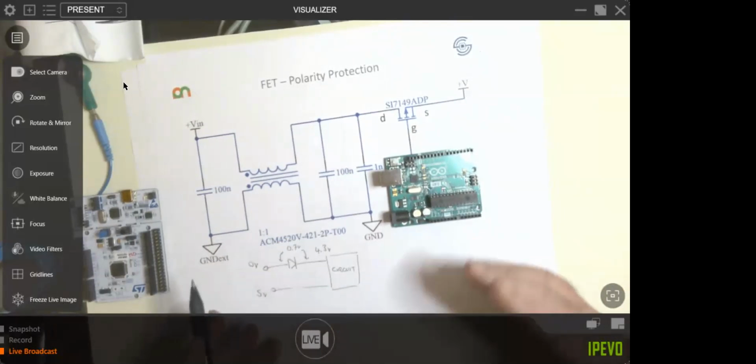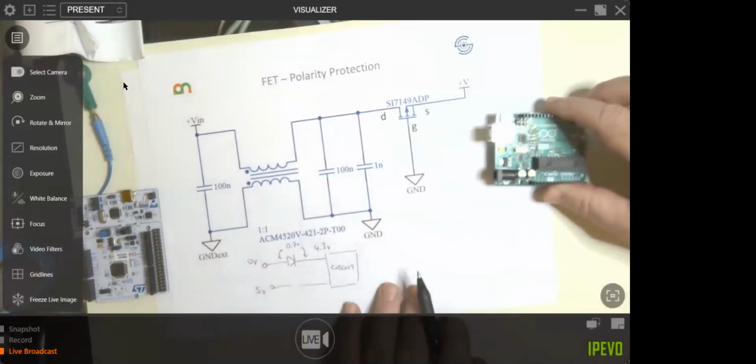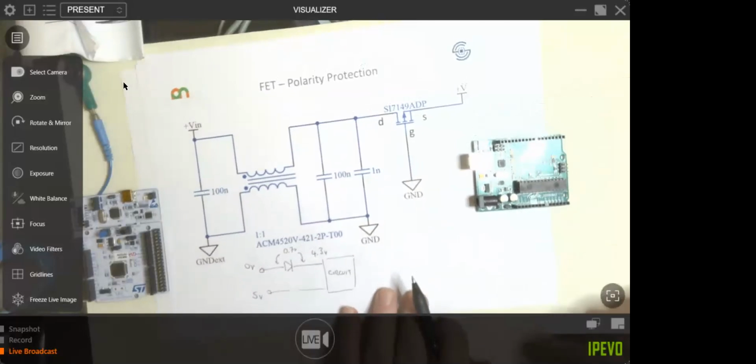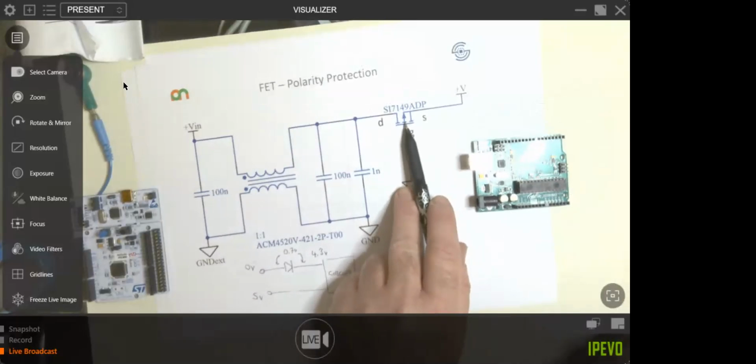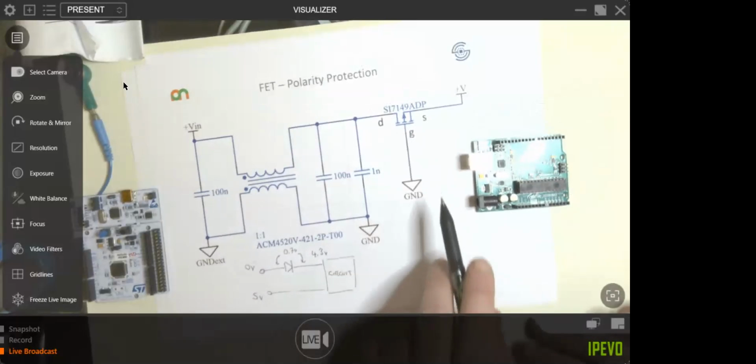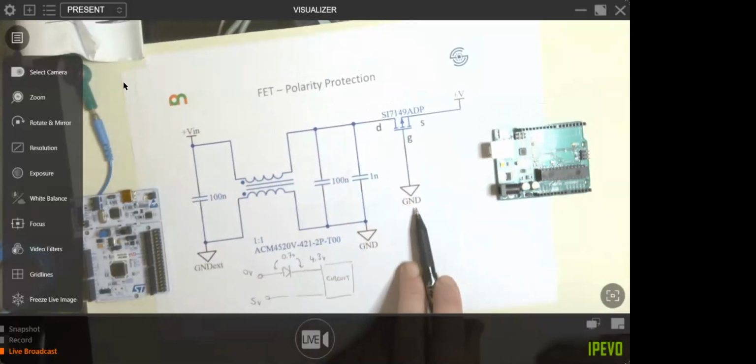But there's a price, as we mentioned. And there's a way out of it. You can use an FET. This is a P channel transistor. The arrow's going out. And the gate is actually tied to ground, or 0 volts, as we often call ground.